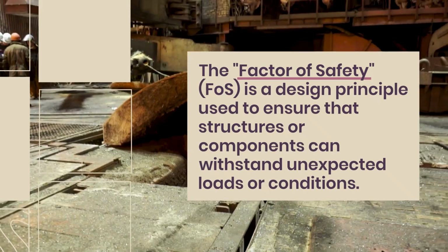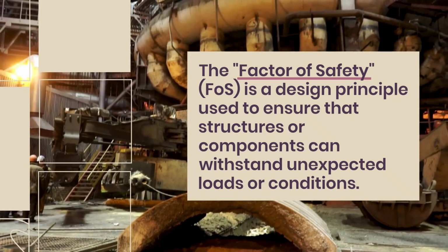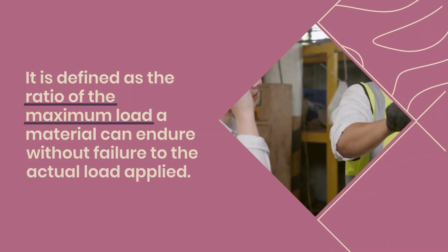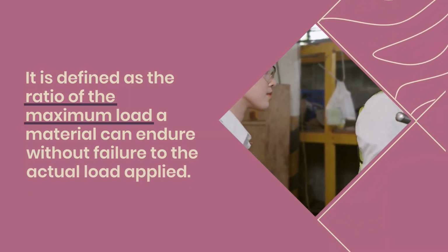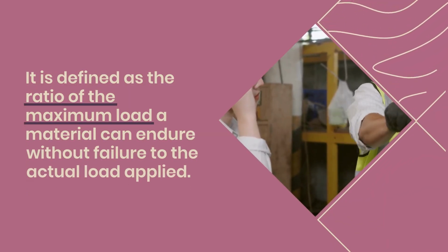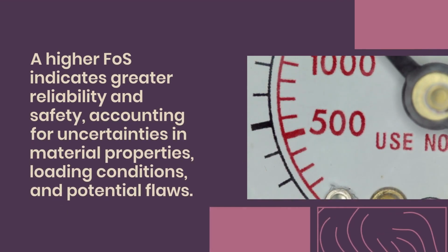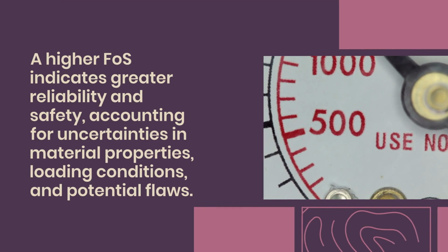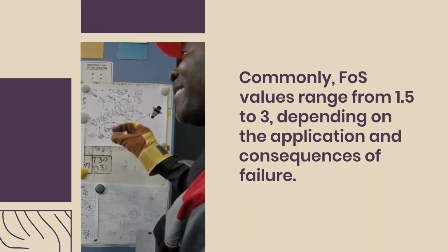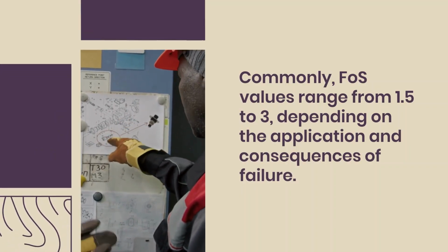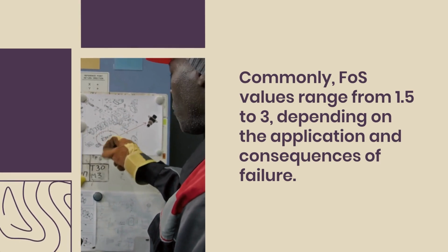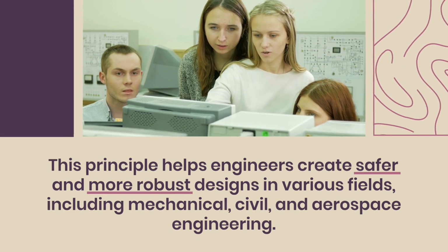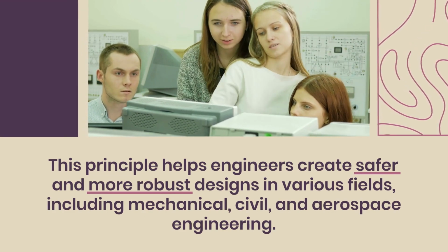The factor of safety, FOS, is a design principle used to ensure that structures or components can withstand unexpected loads or conditions. It is defined as the ratio of the maximum load a material can endure without failure to the actual load applied. A higher FOS indicates greater reliability and safety, accounting for uncertainties in material properties, loading conditions, and potential flaws. Commonly, FOS values range from 1.5 to 3, depending on the application and consequences of failure. This principle helps engineers create safer and more robust designs in various fields, including mechanical, civil, and aerospace engineering.